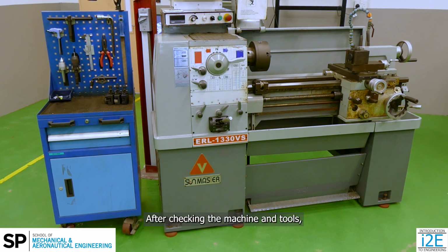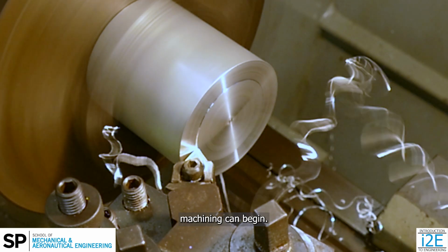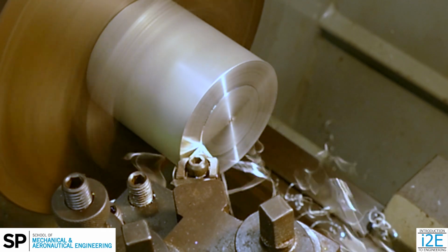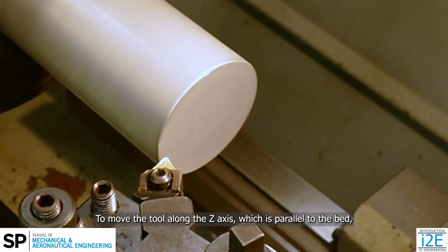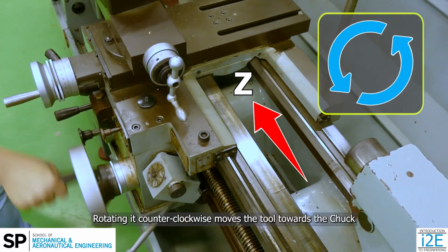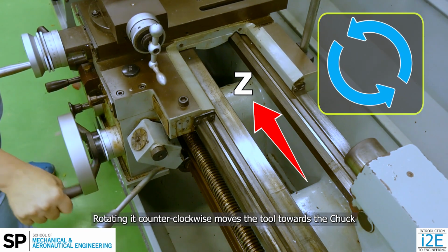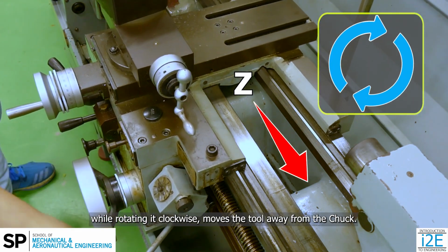After checking the machine and tools, and setting up the correct spindle speed and tool, machining can begin. To move the tool along the Z-axis, which is parallel to the bed, the carriage handwheel is rotated. Rotating it counterclockwise moves the tool towards the chuck, while rotating it clockwise moves the tool away from the chuck.